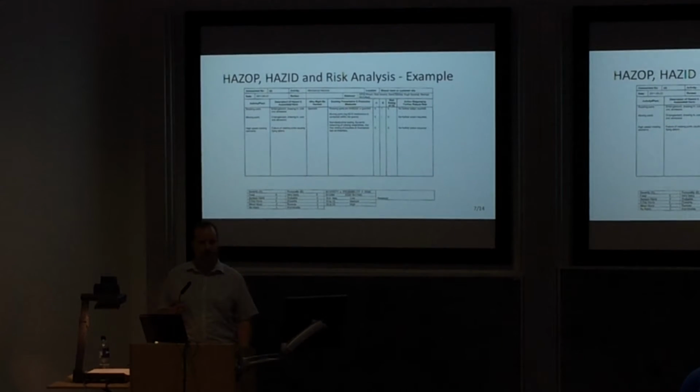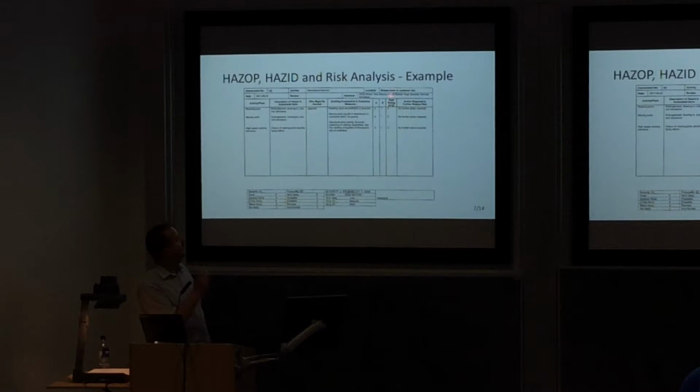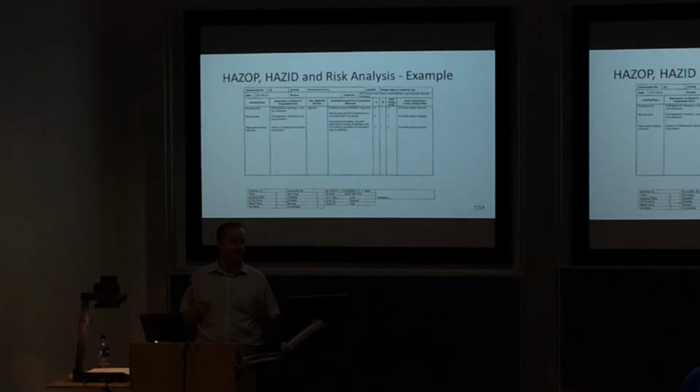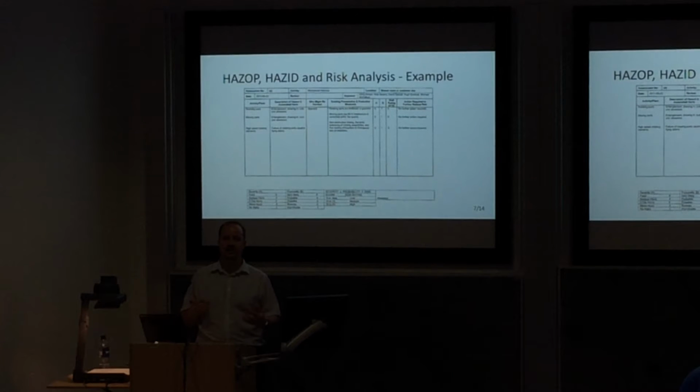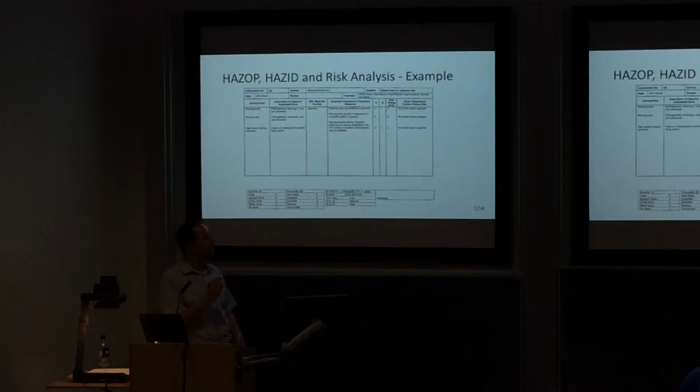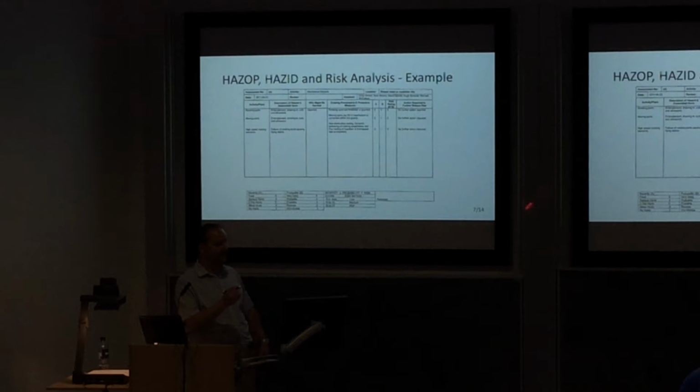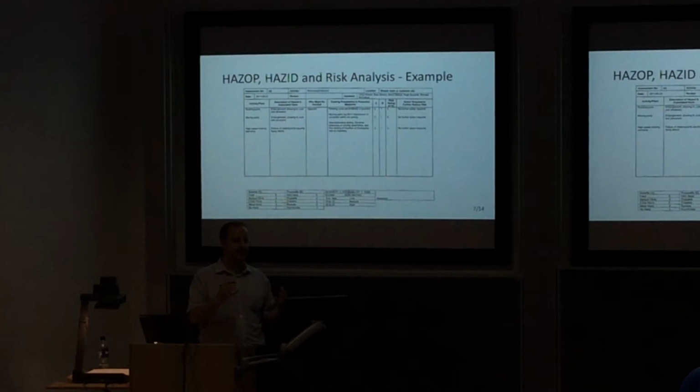So, drawing on that, this is a risk assessment. I know you won't be able to read it from here, but it's in your material. This is one that I did in 2011, and it was based on the mechanical hazards of a large piece of rotating machinery damaging an operator. So in this example, we were looking at rotating parts, the first section, and we're saying that the harm which could occur from exposure to rotating parts is entanglement, drawing in, getting crushed in the machinery basically.